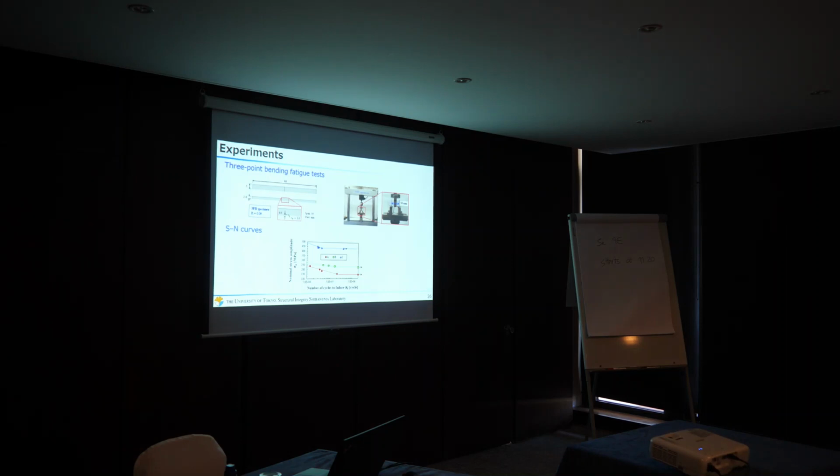Okay, thank you. I see. How do you see that? Because the stress intensity factor is derived based on elasticity, isotropic, homogeneous conditions. But you are inserting the grain boundaries. Don't you think this somehow loses some connection to the basic assumptions of the linear elastic fracture mechanics approach?